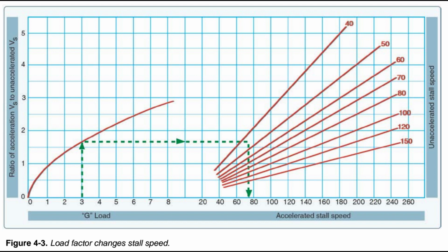The pilot should always be aware of the consequences of overloading. An overloaded aircraft may not be able to leave the ground, or if it does become airborne, it may exhibit unexpected and unusually poor flight characteristics. If not properly loaded, the initial indication of poor performance usually takes place during takeoff. Excessive weight reduces the flight performance in almost every respect.